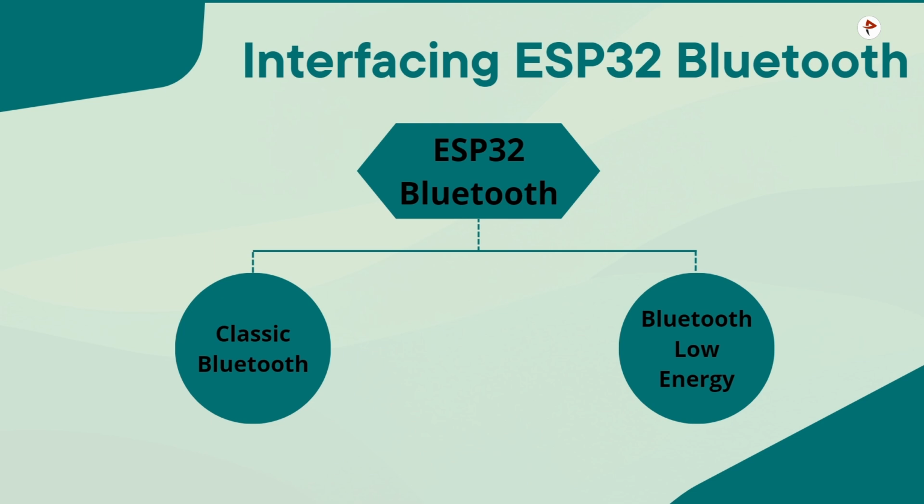controller. What this means is that after receiving data from a Bluetooth device wirelessly, the Bluetooth controller in ESP32 transfers this data to ESP32's processor over serial communication. Similarly, in order to send data over Bluetooth, the processor of ESP32 transmits data to the Bluetooth controller using the serial interface. So we will use this information along with a dedicated Bluetooth serial library to transmit and receive data.